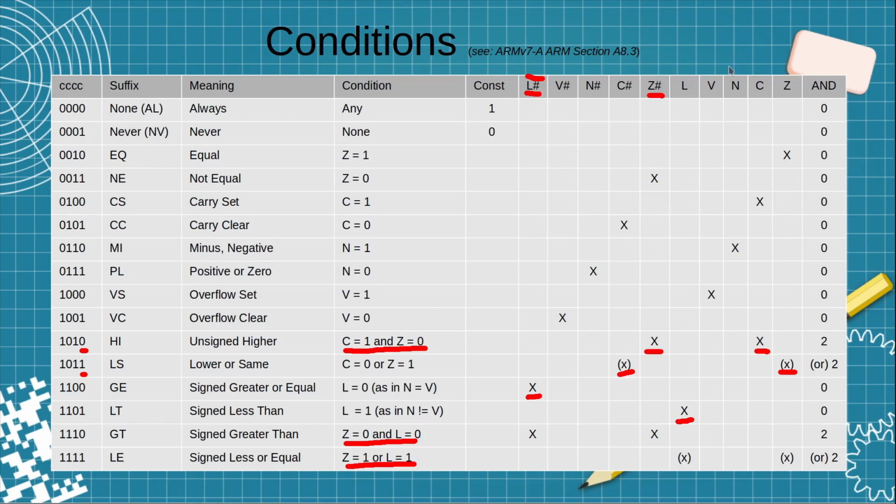Well, that ultimately means that I can get down to a 74HC151 with an exclusive OR gate to handle this least significant bit to determine if I'm presenting the natural state or inverting. And then I just present the results of my 151 as one side of that exclusive OR, a 1 or a 0 to the other side of that exclusive OR.